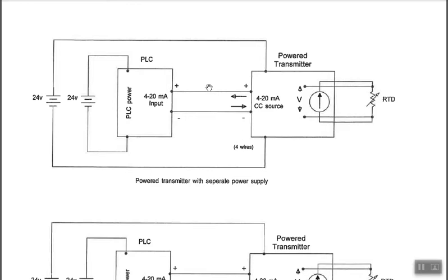I mean, you could put an analog opto isolator right here. Maybe not opto, maybe transformer isolation, but whatever type of isolation, that would be a typical thing to see. And everything stays pretty simple as far as the drawing goes, and nicely isolated. You can see that, right? You got your separate 24 volts out here. You got your isolation here. I think you can see you've done a nice job of isolating the PLC from the rough and tumble world that's going on out here.